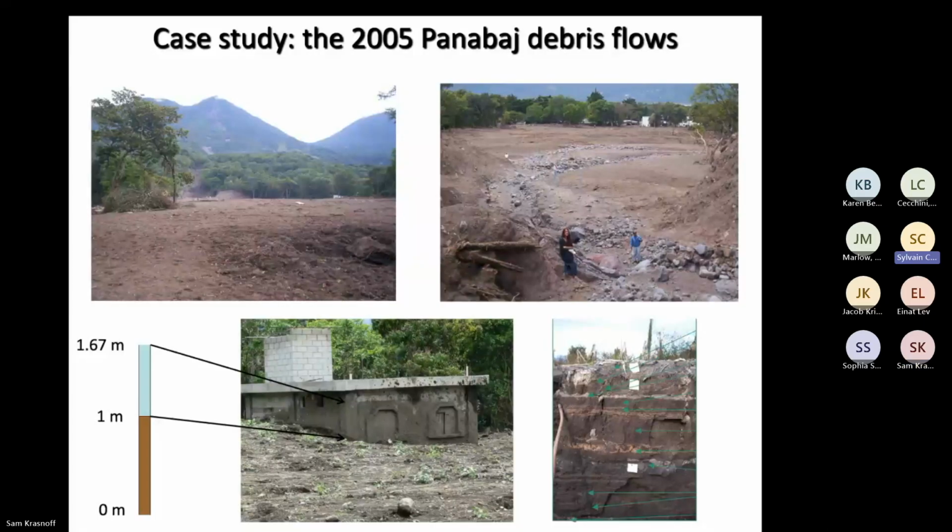on the top part of the flow, basically showing you how we can estimate, for example, the solid fraction inside a lahar by just looking at the depth of this water splash on this, I believe there was a hospital, and then the thickness of the deposit that is below. You can do a ratio of this and try to get the volume fraction of solid. You've got to be careful a little bit because the splash is going to create a momentum.